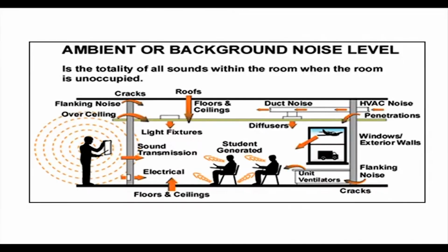But the stage I require to be a reflective surface, so I can make a concrete stage with a high reflective coefficient, or the front of the stage also I can make with a high reflective coefficient. But in the rear part, the floor also has to be treated as diffusive, and in the rear part I have to treat the floor with a very high absorption coefficient. That is nothing but a carpet.